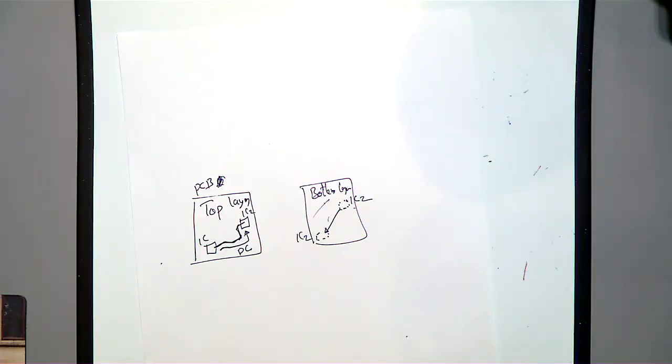This is an important concept when you are designing a PCB at high frequencies, because you always have to keep in mind, even in your PCB design, how the return current is flowing. Otherwise you will get confused with the different planes. Once you are clear on how the return current is flowing, then you know how to design the ground plane, and you don't have any confusion.